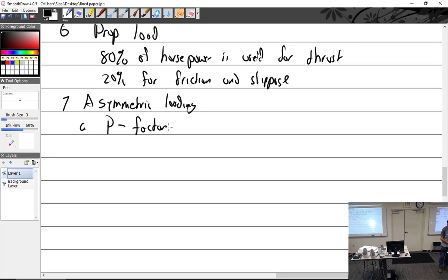So, on this particular aircraft that we're flying, I know it's a wrong prop to bring in here, because it's going that way, which side is taking a bigger bite? It's the descending side. This side over here is taking a much bigger bite. So it's got an asymmetric load. This has got a much higher load than that side. And so which way is it going to make the airplane go? Right. It's going to want to go this way, shoot off that way.